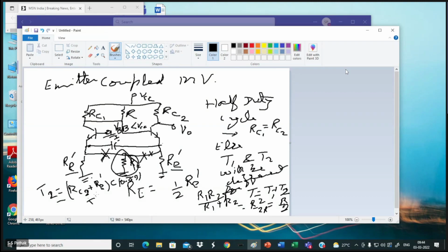And after that, this emitter voltage has now reduced because the charging of the capacitor is subtracting from that voltage. This voltage is now coming close to cutoff. So this will go to your active region or go to your cutoff.